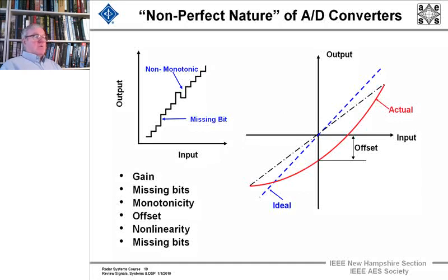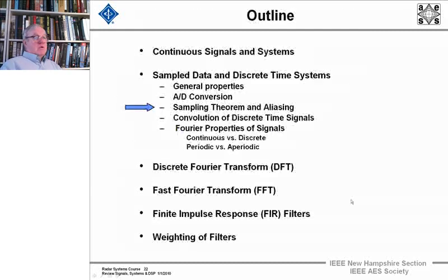And these are things that when you go to purchase an AtoD converter, you have to understand that you're getting the real deal and set up systems so that a product coming out you know is that good. Because if you have a nonlinear box between your analog signal and where you're doing your digital processing that's optimum, that nonlinearity transformation in the AtoD converters can give you big problems if the nonlinearity is large enough. And we'll go on to the next segment.